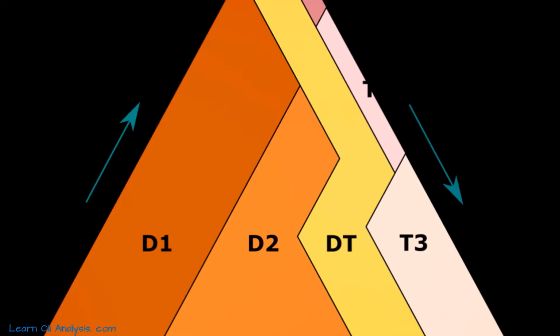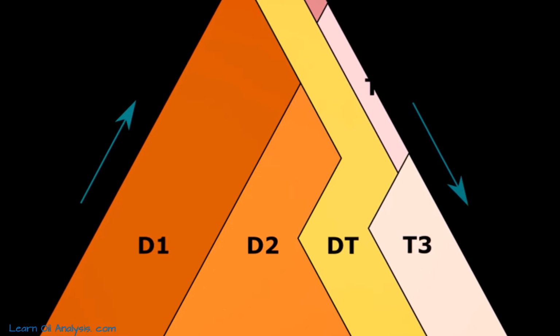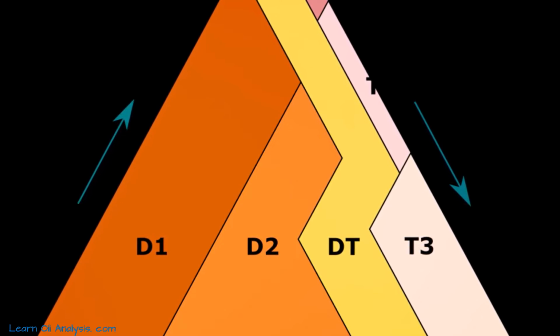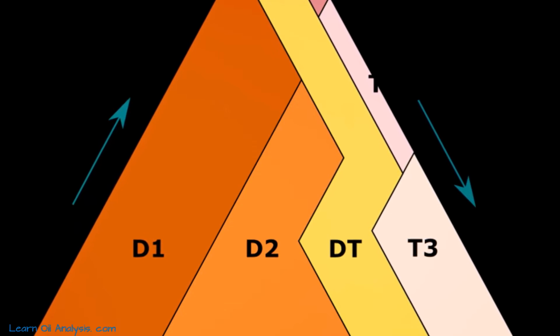Graphical methods also play a big part in DGA diagnostics. Another Goliath in the industry, Mr. Duval, invented the triangle and pentagon methods. These methods plot key gases on a triangle or pentagon diagram to help identify fault zones. By placing the gases on this graph, we can see where they fall and quickly identify potential issues.